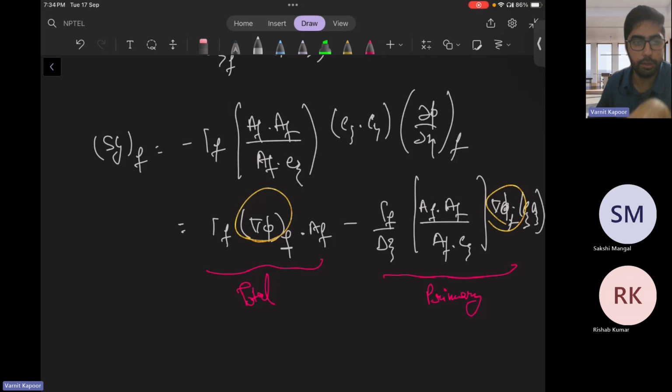So you can calculate the total value and subtract the primary gradient to get the secondary gradient. This is how all these commercial and open source codes work for the calculation of the gradient on a particular phase, for calculating grad phi.